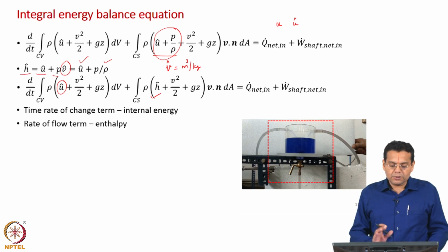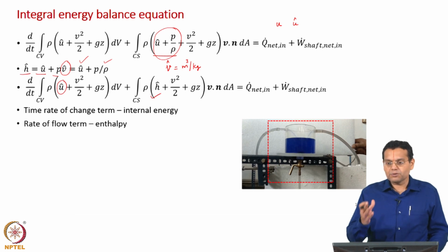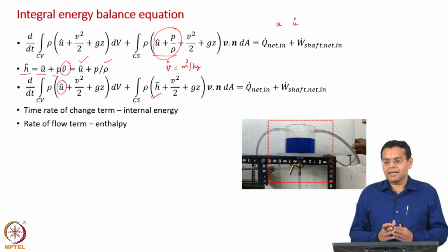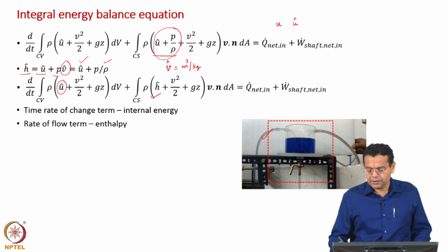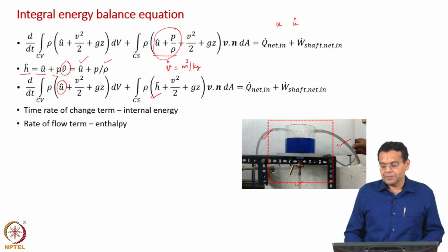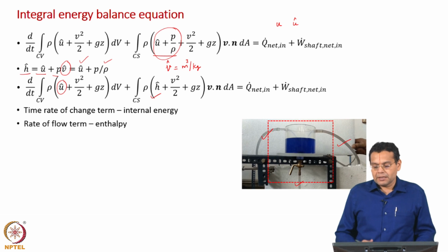Also, when you look at enthalpy, what should come to your mind is internal energy plus flow work. Moment you look at enthalpy, let us say we are looking at a stream flowing in and out. When we first came across it, we said the stream contains energy, and the three parts are internal energy, kinetic energy and potential energy. Now, slightly refine it and say that the stream carries enthalpy, kinetic energy and then potential energy.